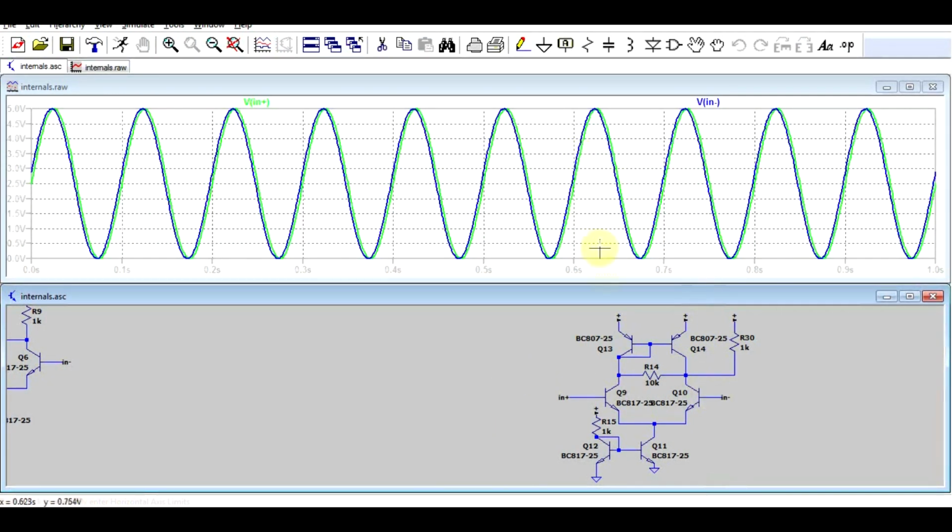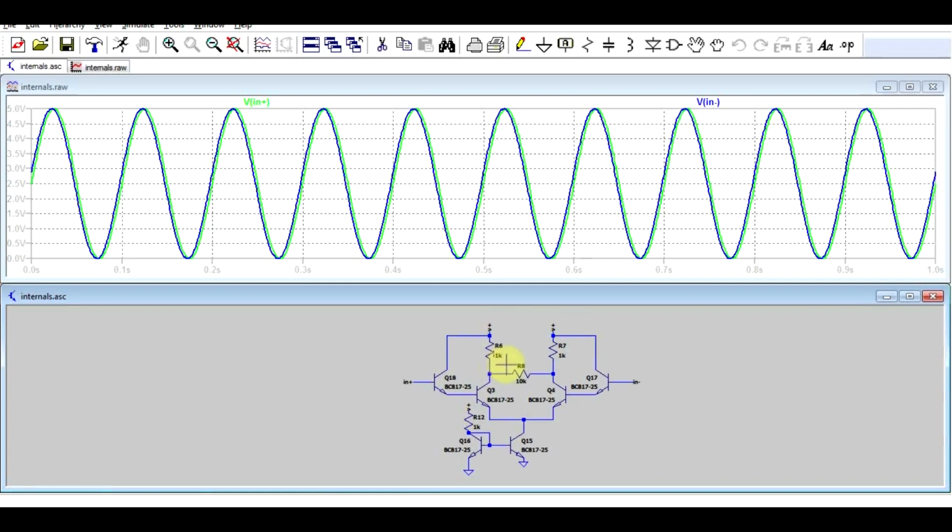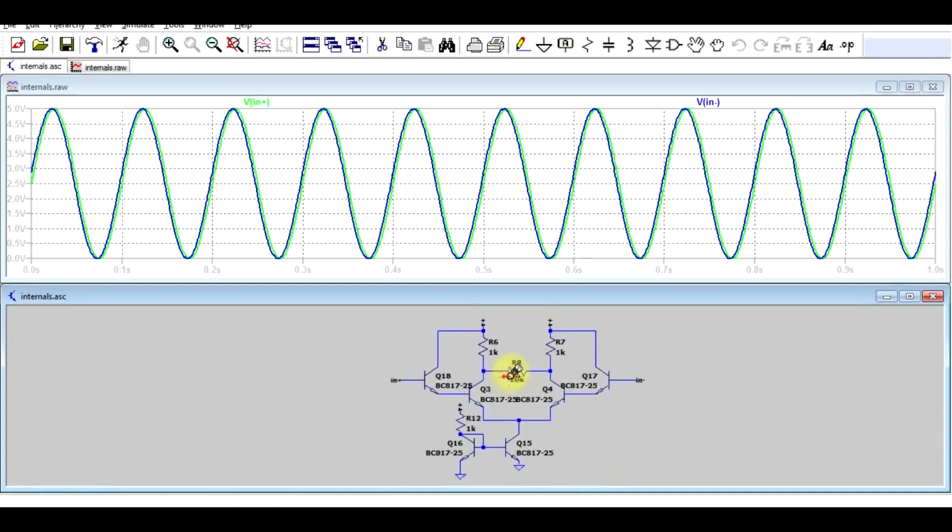How can we get at least one of our inputs to go to a certain rail? Well, we can use this sort of input stage. So what makes this different from the previous one? Well, we've got a small difference. We've got two transistors on either input. This means that if we have on one of the inputs the supply voltage, so 5 volts, we've got on the emitter of the first transistor minus 0.6, so 4.4. On the emitter of the second transistor, again minus 0.6, so 3.8. And then in the emitter of this transistor, we've got 3.8 plus 0.2, so 4 volts.